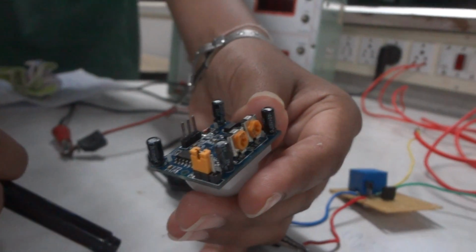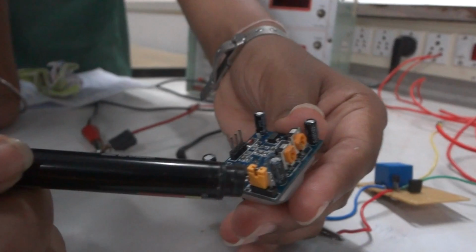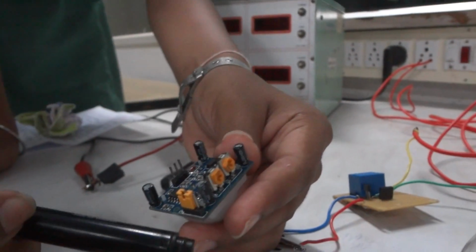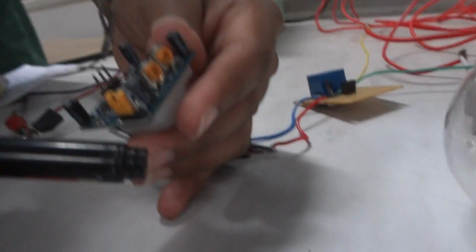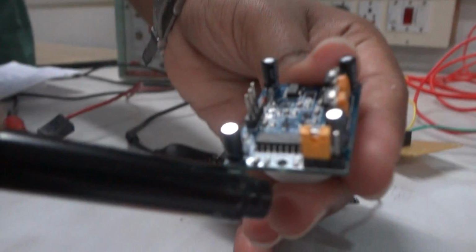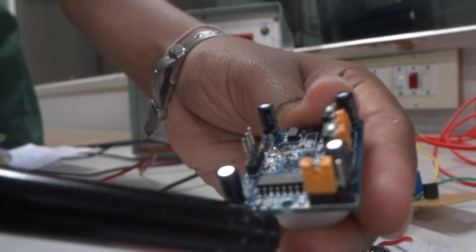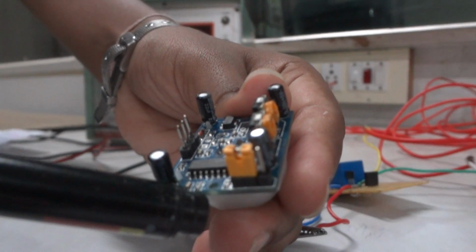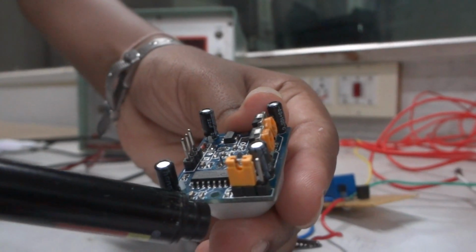Now if we connect this jumper between the inner corner and the middle pin, then the bulb will stay on all the time till there is any motion. This one is called repeatable triggering, and the jumper is said to be in H position.